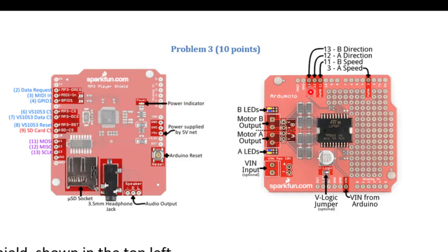The fix for this would be to use different pins for the motor board. So use some of the pins that aren't used by the MP3 player. And you'd have to either not stack these, you could wire them separately, you could solder wires in here and then add them onto the Arduino yourself, or you could cut the traces and move them around or something. But when they're built and designed like this, it's a little harder to fix, but not impossible.